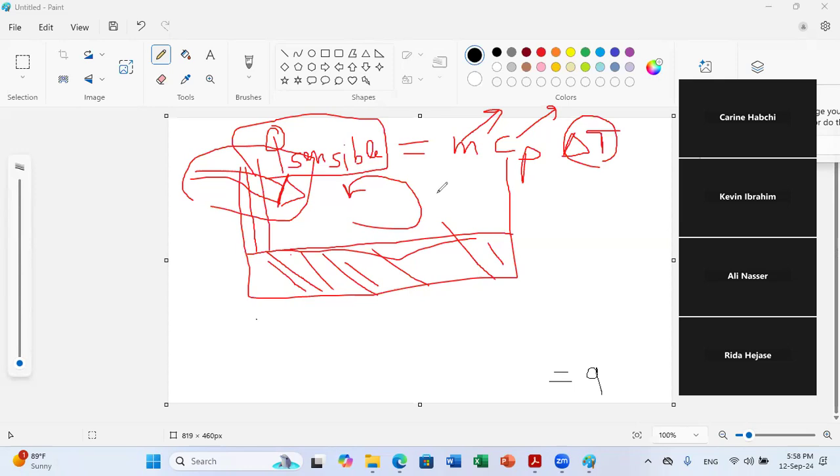So here, what will happen is that if we use appropriate thermal storage with high mass and high specific heat, we can store this excess of energy during the day. And when needed, it will release it back to the inner environment. So during the night, when you have a drop in temperature, this will work especially in regions where you have high differences in temperature between the day and the night.